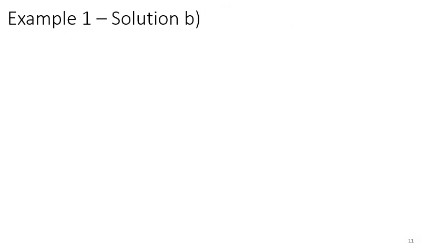Alright, for part B of this example, let's say you have a liquid feed of 100 mole per hour, at the boiling point given in the previous example, fed to the distillation tower at the given pressure of 1 atm, and to be fractionated so that 90% of component B is recovered in the distillate, and 90% of component C is recovered in the bottom. So you have to calculate, number one, the moles per hour and composition of distillate and bottoms. Okay, let's do that first.